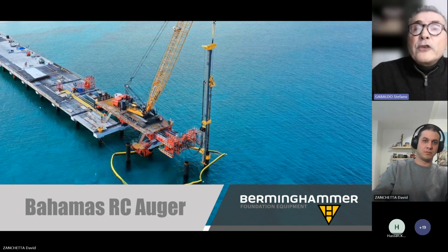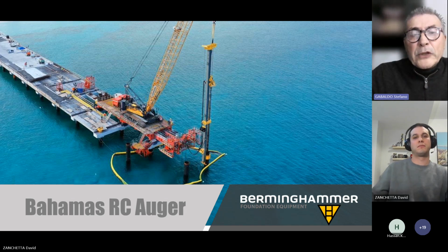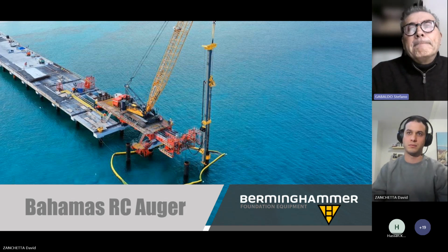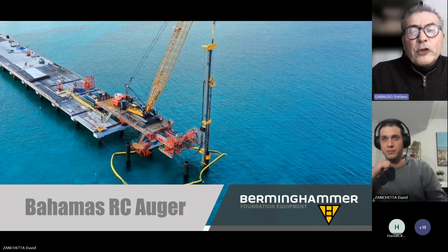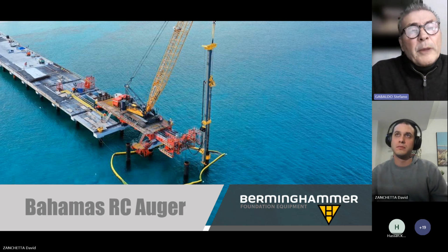Here we are on a jetty, and we're constructing it requiring the usage of only one crane. There is no room for anything else. And we wanted to separate the land equipment, and we wanted to actually get rid of the land equipment so we were not subject to sea conditions. So we had a cantilever travel system that basically positioned the template for the piles.